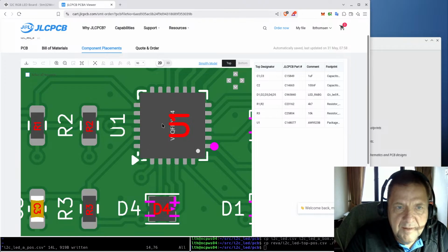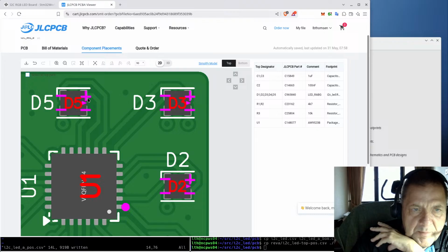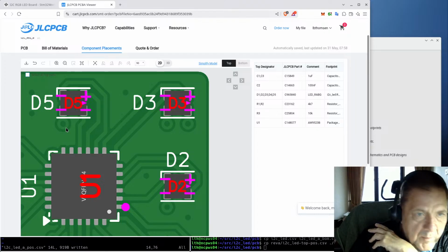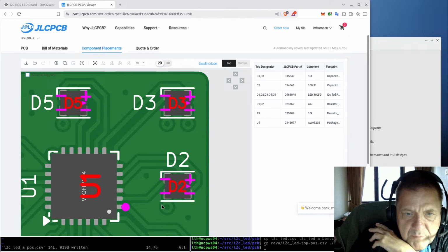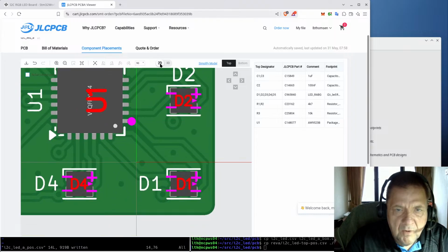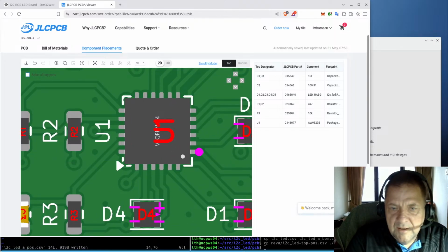The other one that goes wrong is typically diodes. There you can see we have the plus up here, indicating that is pin 2 actually. So we have pin 1, but pin 2 is down here. Remember when we were doing the PCB, I had to put the VCC into this pin. That is the one they indicate with a plus. So in other words, these all need to be rotated 180 degrees to fit.